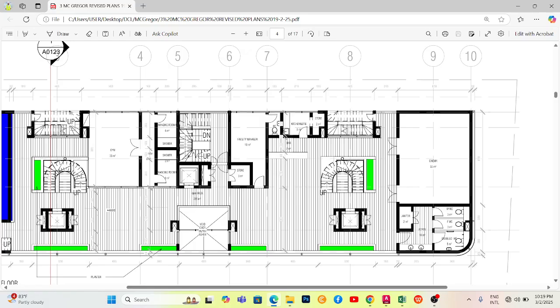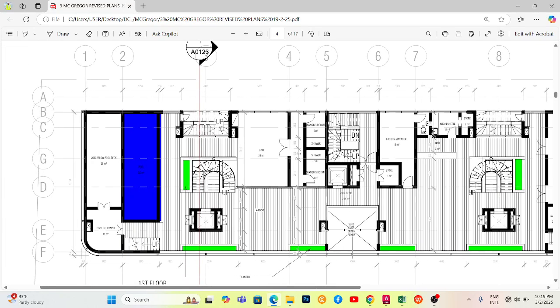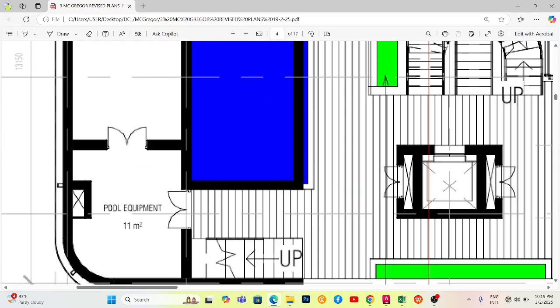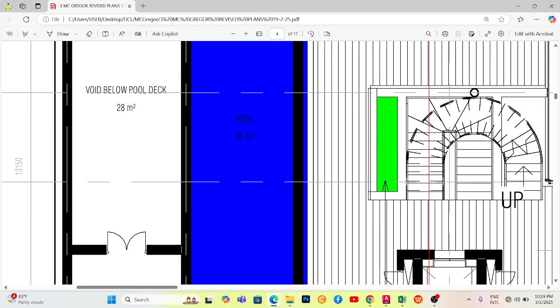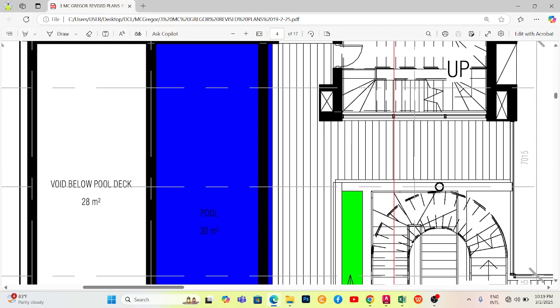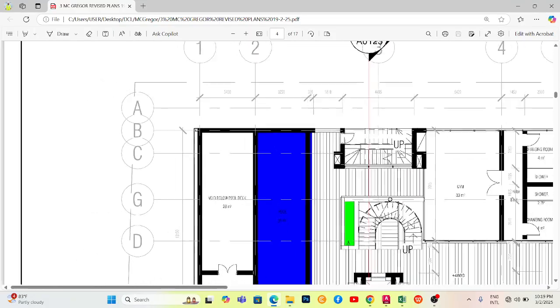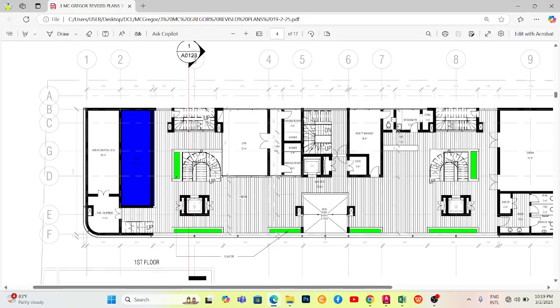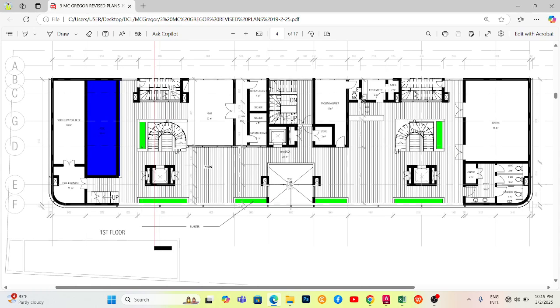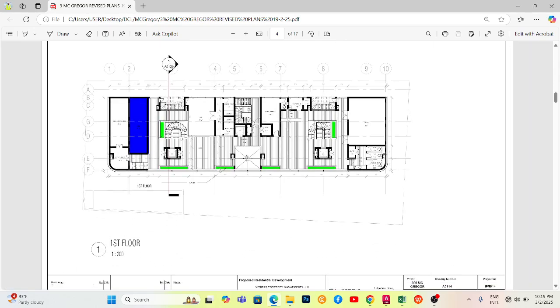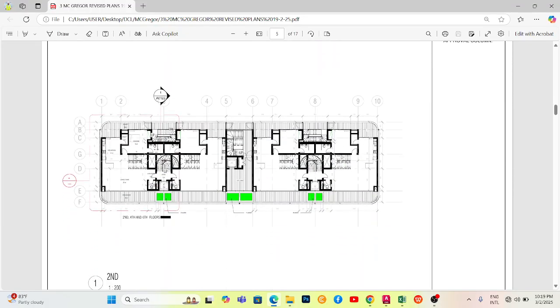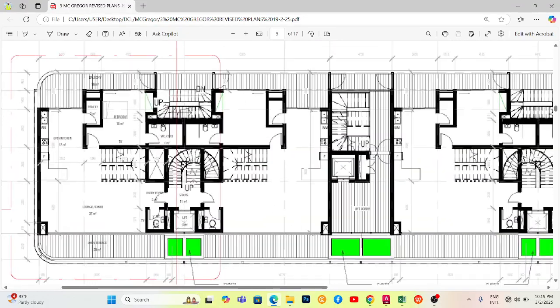Then there are some of them that will want you to use 6 inches blocks for their walls, and there are some 9 inches blocks. So they will definitely give you those details, like the thickness of their wall. You will see it there that it is clear. Some of them will not be as thick as others. So that place you need to pay attention to as well. I think there's nothing really too much about architectural drawing once you have paid attention to all those things.